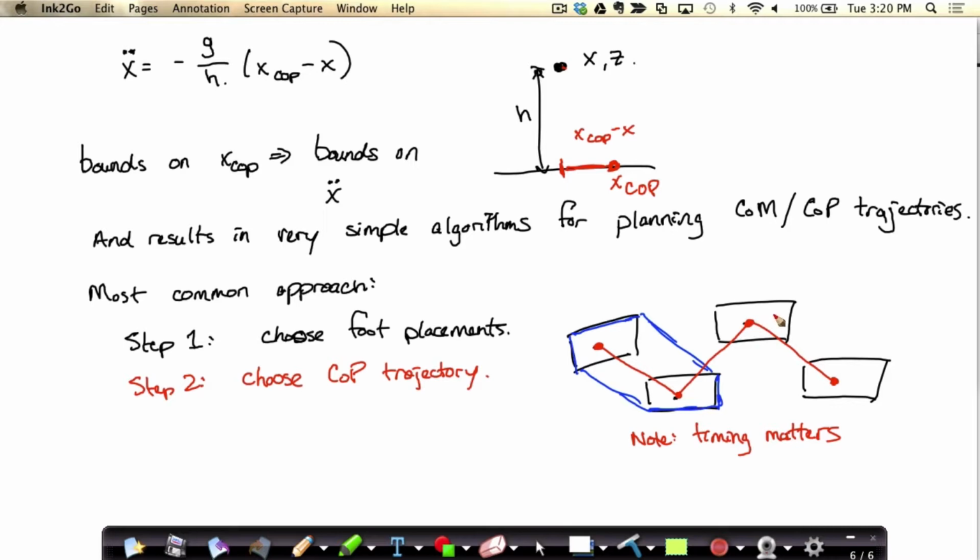This is a very different view of planning than anything we've talked about so far, right? So far, we've been saying: let's formulate an optimization, search over joint trajectories for my acrobat, get it up to the top. Now I'm going to hand code the contact forces that are going to control this thing. I'm just going to hand design it, and I'm going to read back what that implies as a constraint for the rest of my system. Okay? It's a very different view of the world. It's a very powerful one.